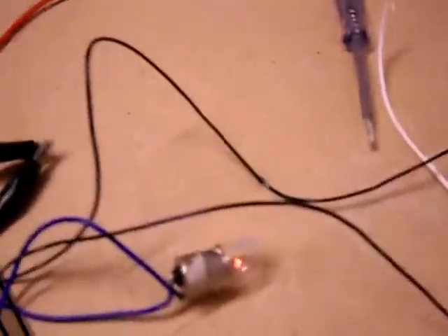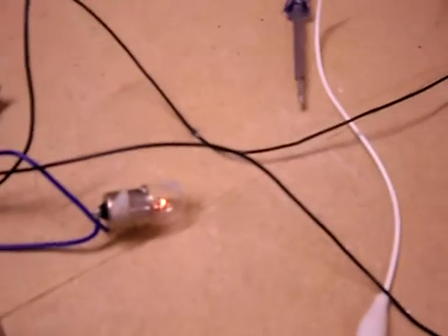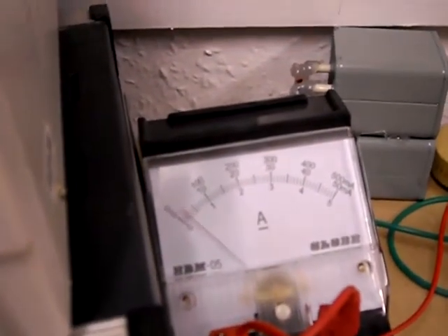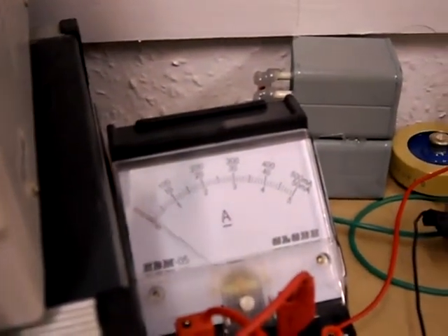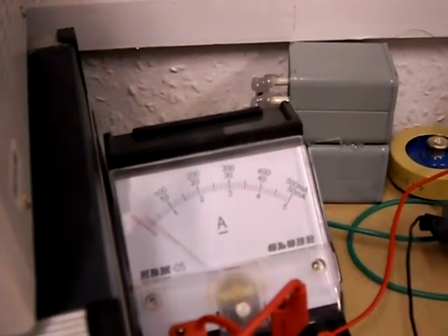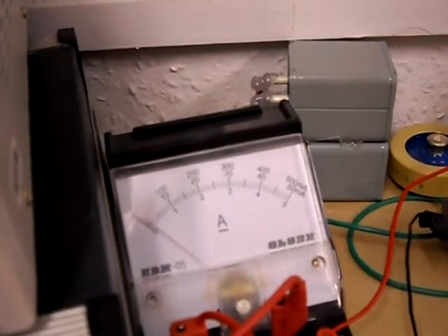It's a shame you can't see the bulb. It's quite interesting. Although it may look like it's on all the time, it's actually pulsating. I can show you the pulsating current maybe a bit better on the meter. You can see the meter moving up and down. If I start moving the coil, if I face it, if I move it around, it varies. That's about 45 degrees. There, see the bulb pulsing. If I lay the coil down, it's still pulsing, but if I move it around different amounts, it alters.